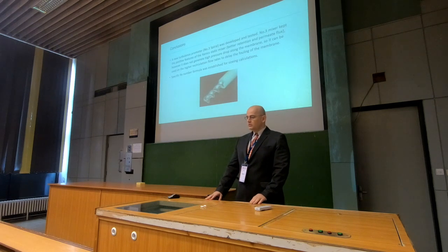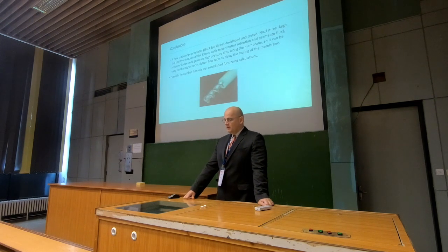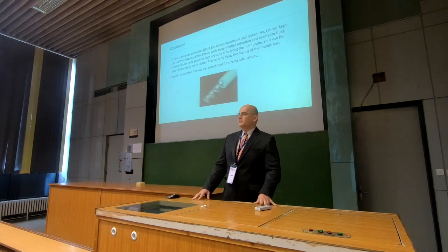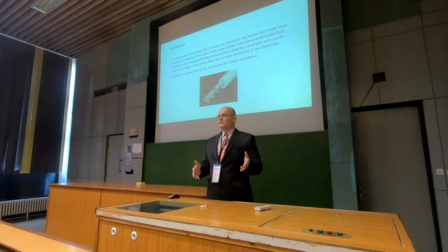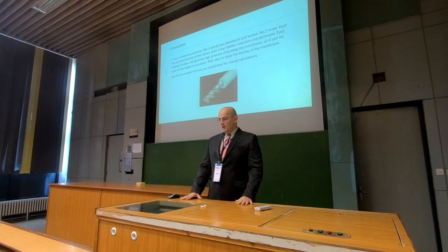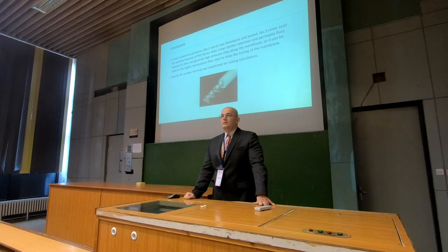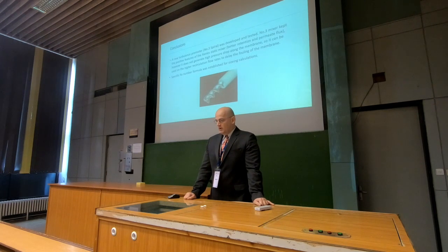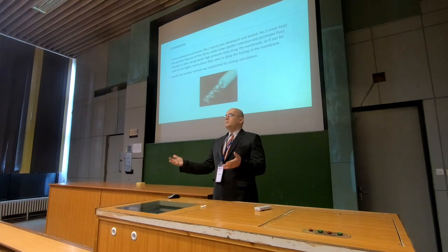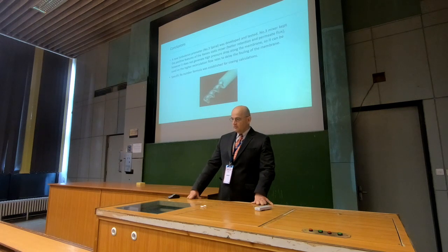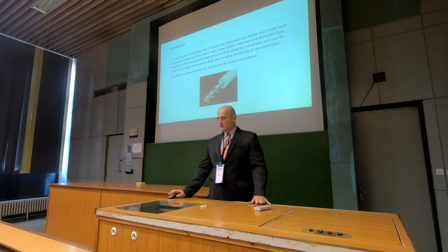Conclusions: a new turbulence promoter was developed and tested, and this new spiral static mixer keeps the positive effect of the Kenix static mixers, the initial flux rate and retention, and also it doesn't result in a high pressure drop along the membrane, even at higher flow rates. This means the fouling of the membrane will be more delayed. And a specific Reynolds number formula was established for sizing calculations.